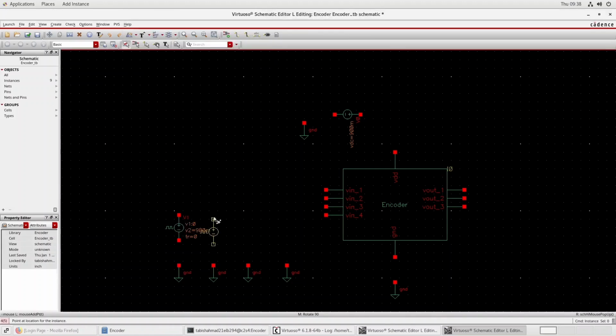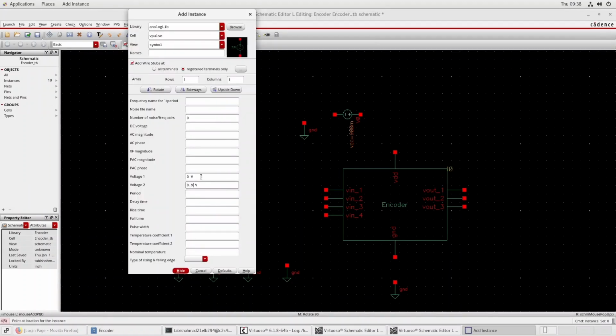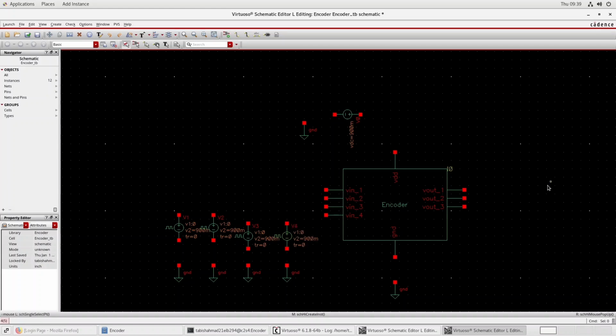So at 2 microseconds, third will be of 4 microseconds, 3 microseconds, okay, and next it will be of 4 microseconds. So basically we have different pulse width pulses which we will give as the input of the encoder, and we will see output accordingly. If it matches the functionality of a priority encoder, then yeah, our schematic is correct. So we will do the connections.